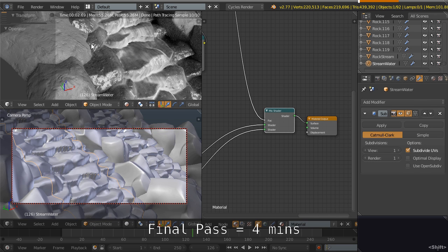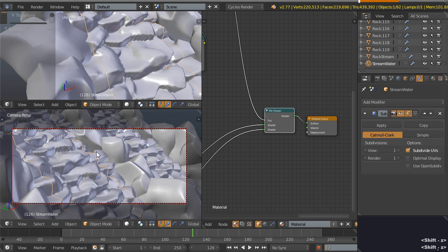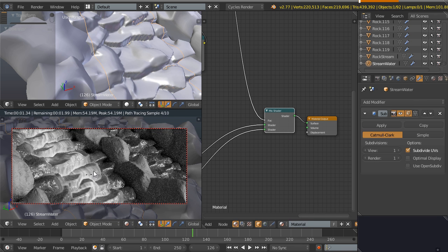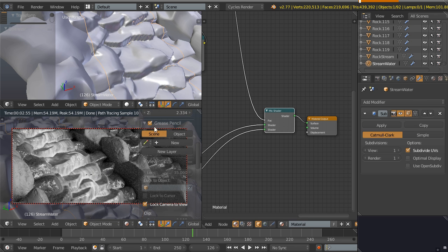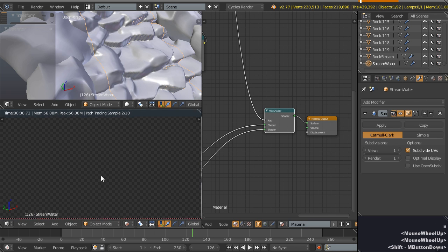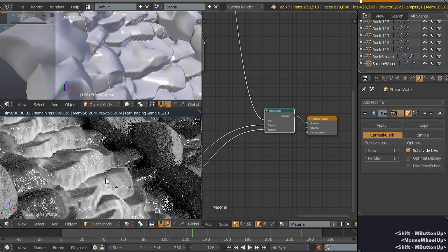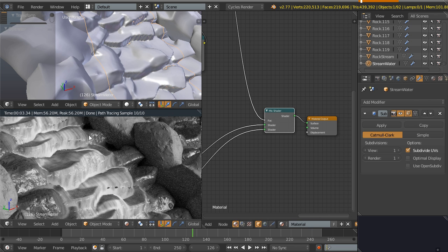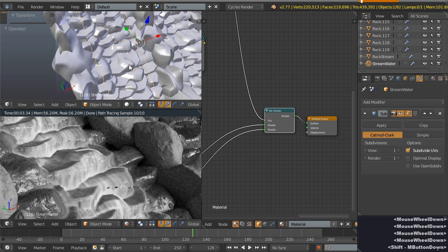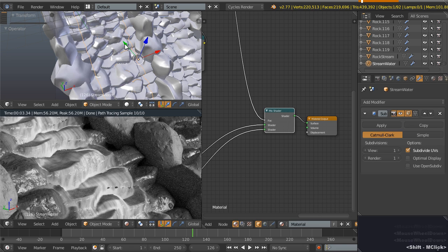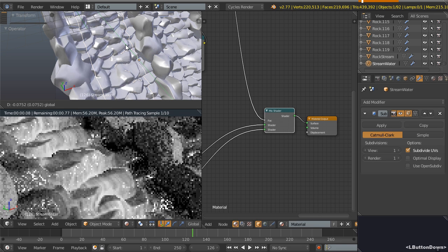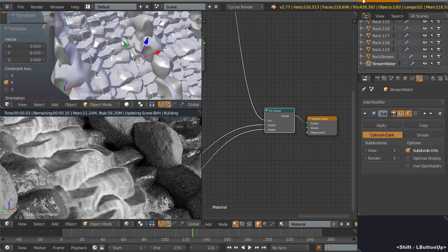We'll start by taking a look at how things are in the camera view. So that we don't move the camera accidentally, let's press N and bring up the property sidebar and unlock the camera to view. Now if we zoom in, we're not going to move that. We can see a little problem here with the rocks underneath this plane peeking through. With this one selected, I'm going to left click and drag on the gizmo on the Y-axis and pull that forward. If we want a little bit extra control, we can hold Shift to get that right into position so we're not moving it too drastically.